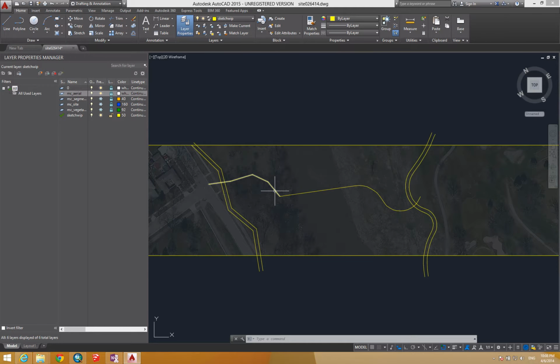And what I've got here is kind of a hodgepodge of polylines. Sometimes, especially if you're about to do an offset, it is better to join these. So you'll be doing polyline edits and explodes quite a lot. And explode will just essentially do what it sounds like. It takes your multiple lines and makes them separate. But once again, polyline edit.